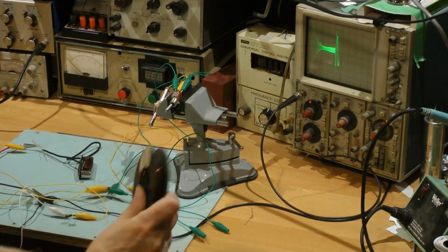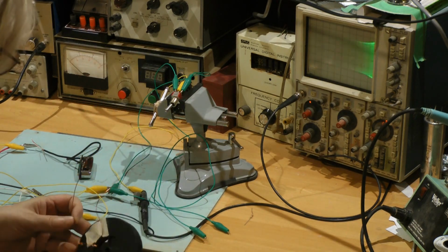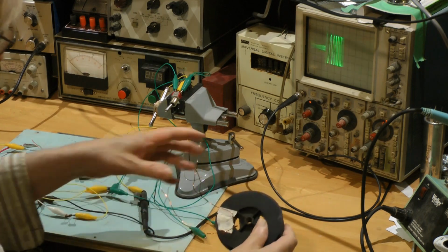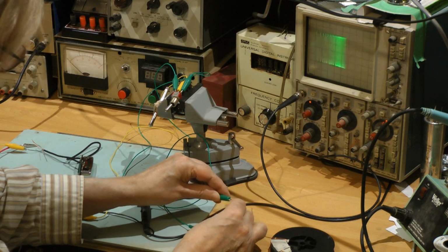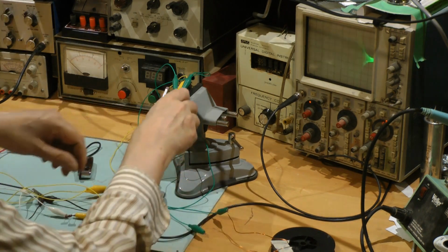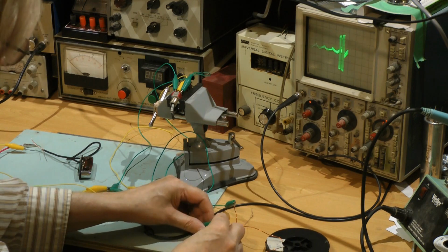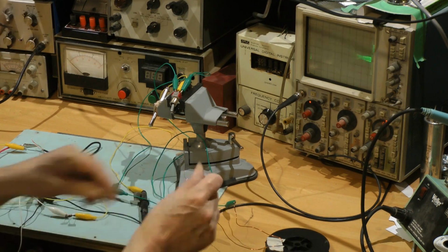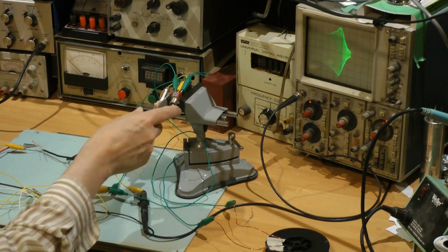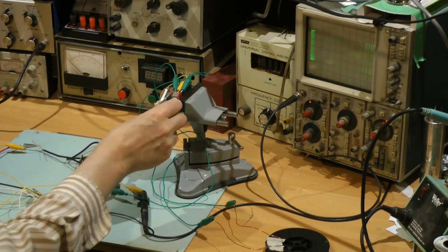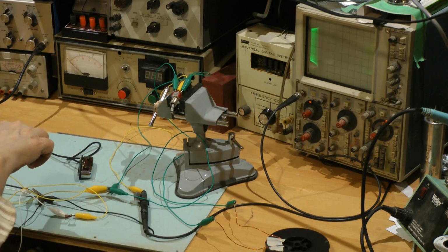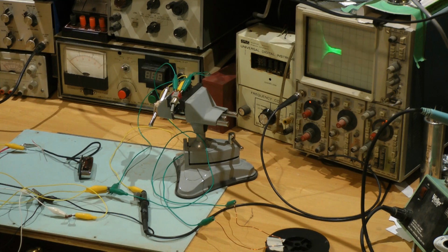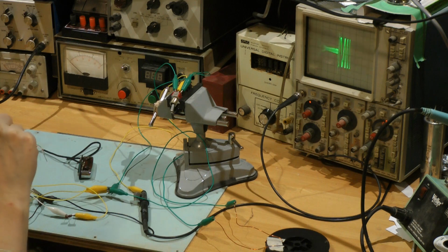Some people worry about coiling up their guitar cord. Well, they'll never get that much of a coil, but if you had a 100-foot guitar cable and managed to coil it up, let's put the coil in and we can see if the coil does anything. Nope, not a thing. Why? Because this pickup's about 2.5 henries. This thing's not even a millihenry. Imagine what your guitar cord would be coiled up. Maybe a microhenry.